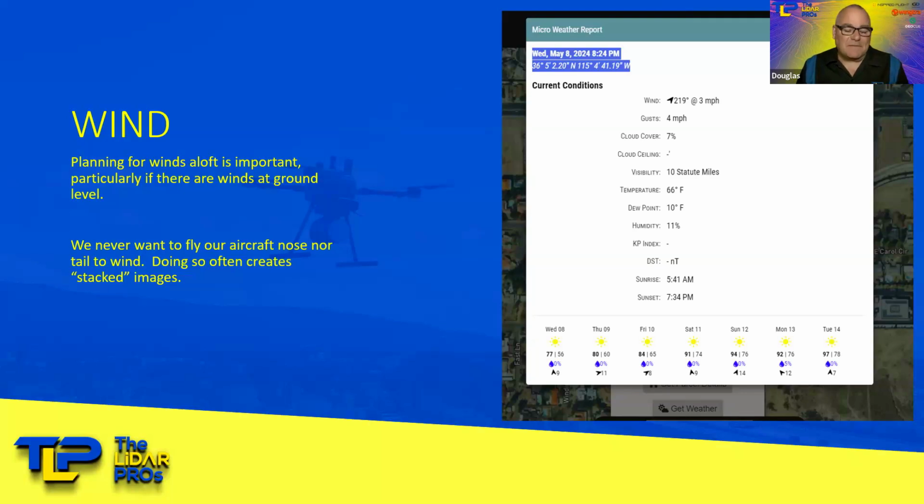There is no safe flight speed for mapping. In other words, if you're going to map with something fairly small and lightweight, let's say the Parrot Anafi, you're going to be limited to winds that are sub 20 miles per hour. If you're flying with something a little bigger, such as, say, the MapTech or maybe some of the Inspired Flight systems, we're just good to go all the way out to about 35 miles per hour of wind.